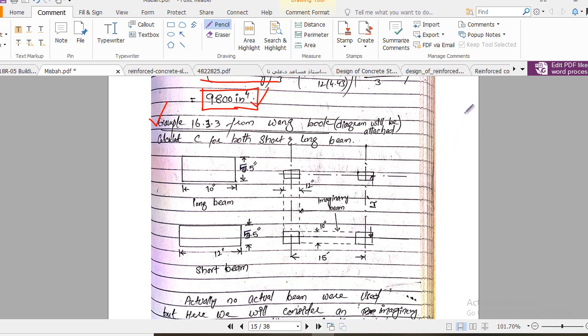For example, let's say you have a slab system and you have a column. Clear? You have a column. If you have no beam right here in this edge portion, you have to consider an edge beam, remember, and the width of that edge beam will be equal to the width of that column in this direction. And then in this case, this will be the section of our transverse beam, this one. So the same case is here.